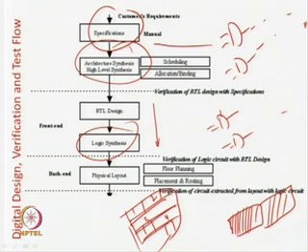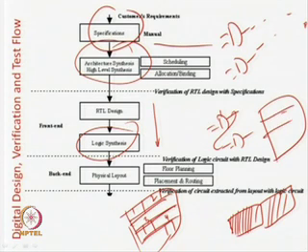So, in physical design, you know which gates are to be used and how they are connected, and all the connectivity information is available from the logic synthesis. It will tell you which gates have to be used, how they have to be connected, and all that information is given in the logic synthesis stage. Now, you have to put these gates and the interconnections in a block, a rectangle or a square, where there are some rows and the gates look like rectangular blocks.